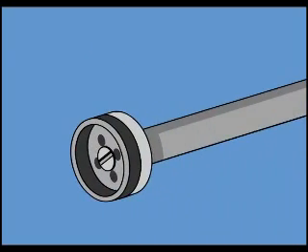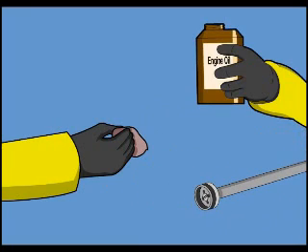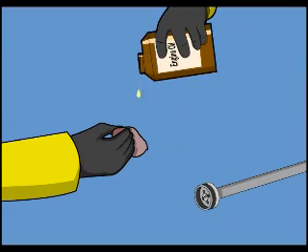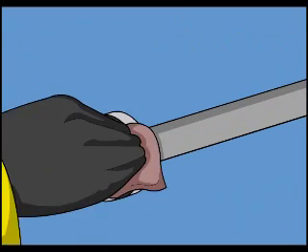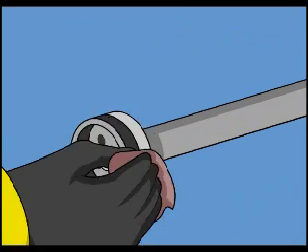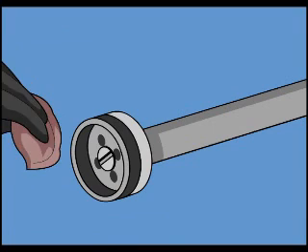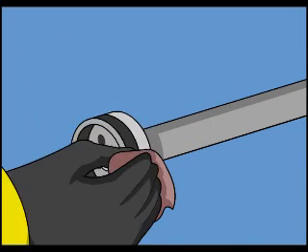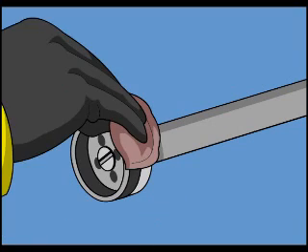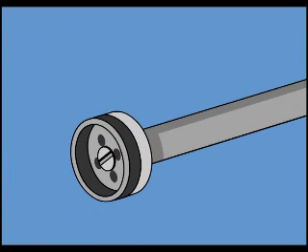If the leather pump plunger cup is dry, soften it by rubbing in some clean engine oil. If it is damaged and needs replacing, unscrew the disc holding the plunger cap and replace. The plunger needs to be oiled weekly, not only when the pump is checked during routine maintenance.